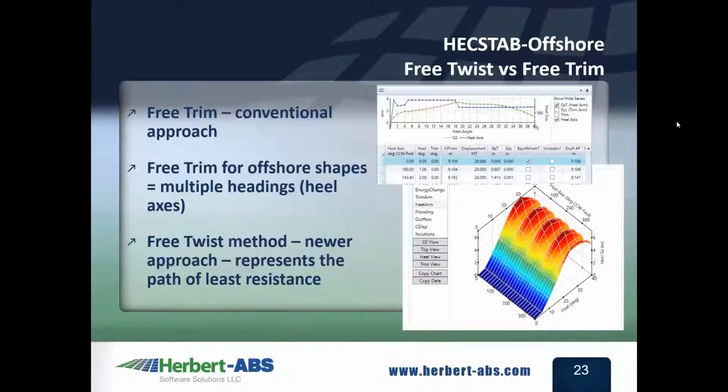Some of the other neat things on the HexTab side, on the offshore side, I've talked about this before. We do have the capability to look at things in a free trim or a free twist type of methodology. The free trim is the conventional approach. You basically specify, give me the stability around this heeling axis. For a ship, that would normally just be the longitudinal axis. For an offshore shape, you might be looking at multiple headings where you rotate around the entire vessel.